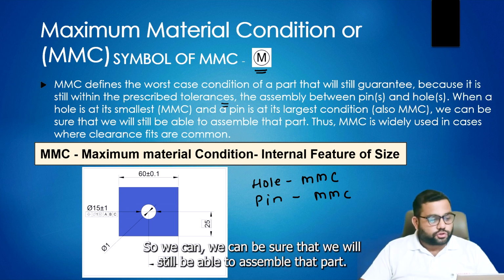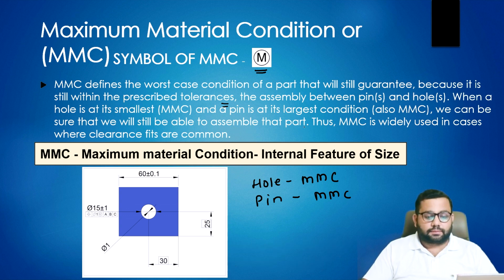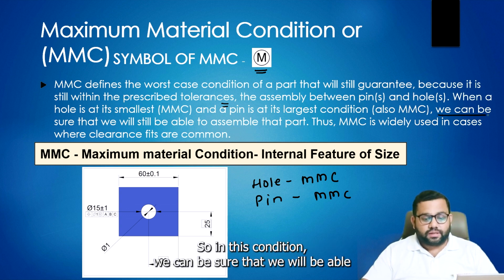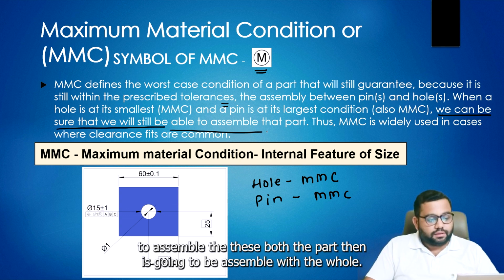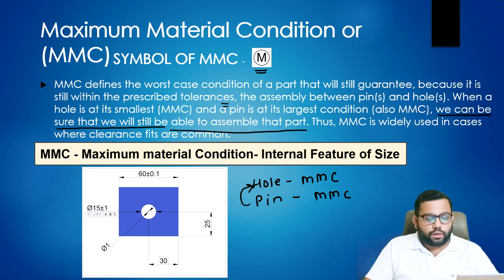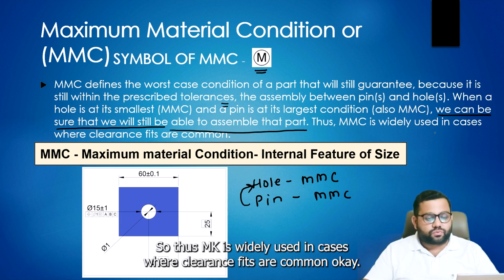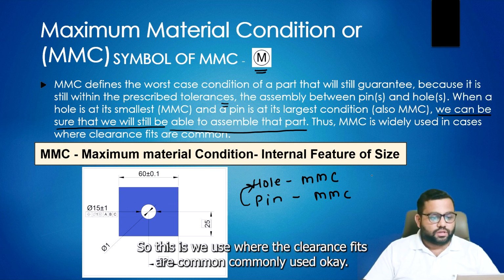So we can be sure that in this condition we will still be able to assemble the parts, and the pin will be assembled with the hole. Thus MMC is widely used where clearance fits are common.